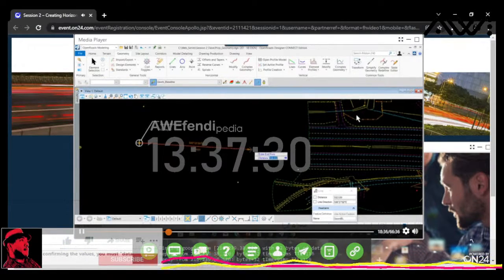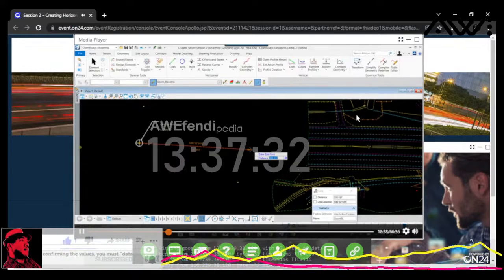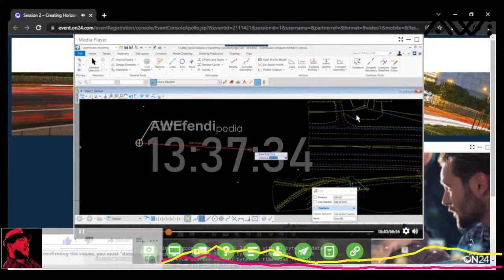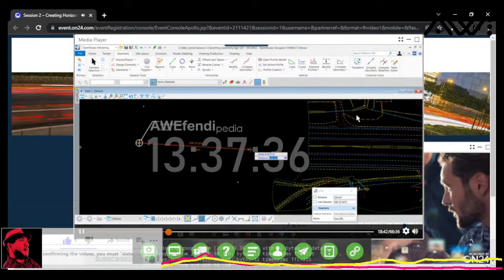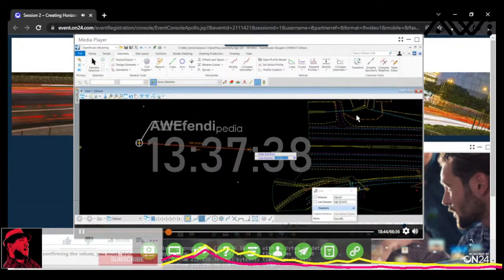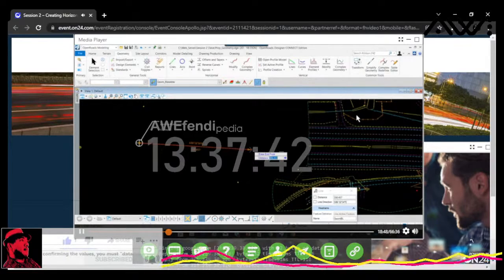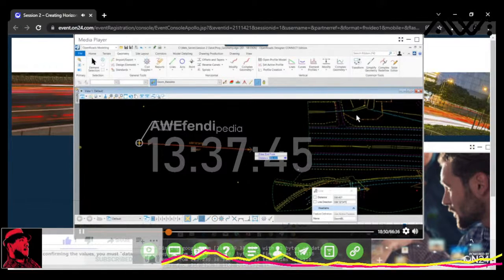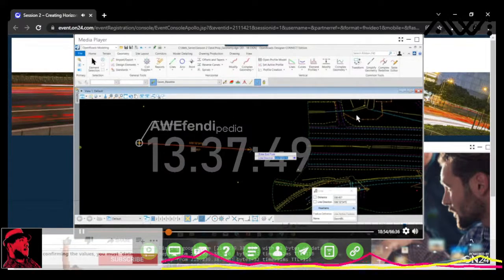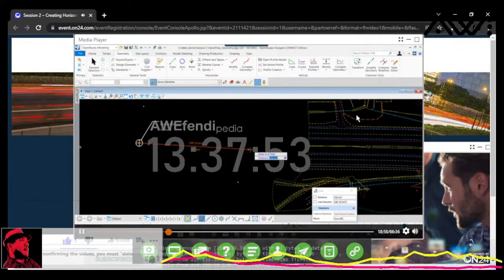On those heads-up prompts, number one, you can key into the highlighted field, as well as the arrows indicate that I can move between information, left or right. So I click the left arrow or the right arrow, and it tabs me through distance and direction that I can use to input data for this particular element. All right? So I'm going to leave it on distance, and I'll just jump back over to this PDF.